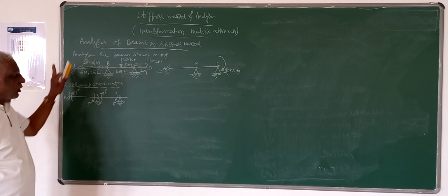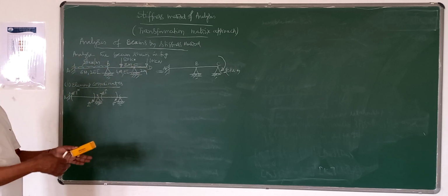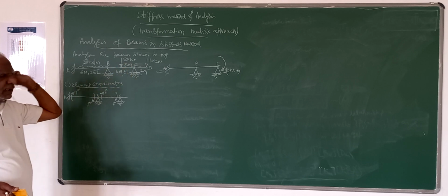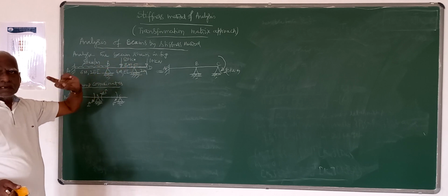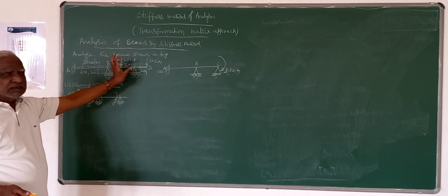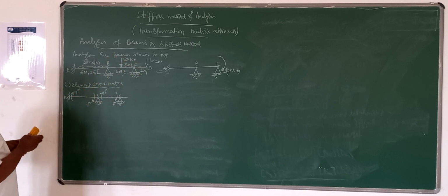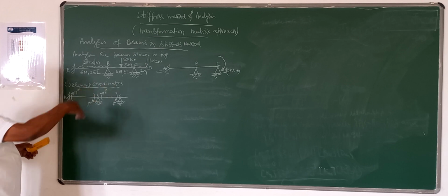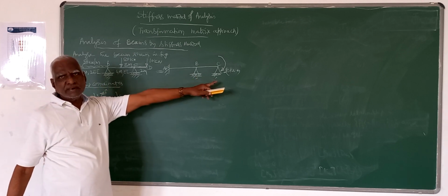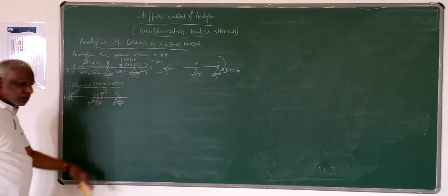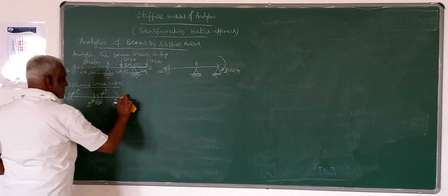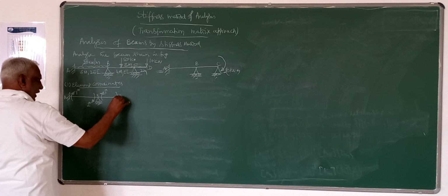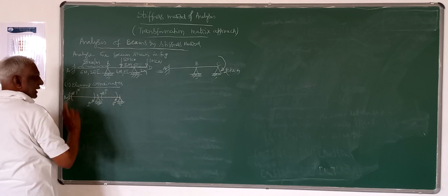Normally, whenever an overhang is given, that overhang is replaced by an equivalent joint moment at the immediate main joint of the structure. Similarly, if the overhang is given on the other side, there also you can replace it by an equivalent joint load and do the analysis. So that particular joint load I have taken. That's why here I will take only joints A, B and C.